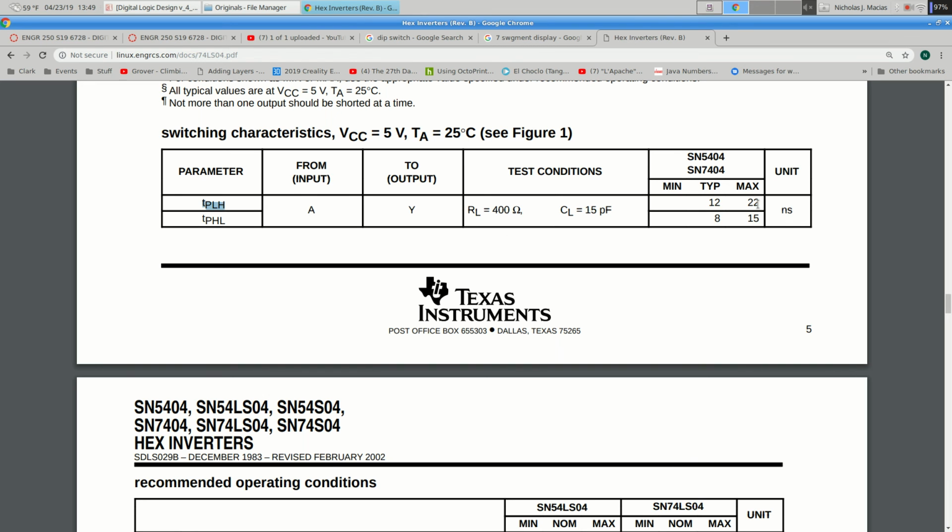And this is always present. There's always a propagation delay, and sometimes we can ignore it. When we're building a 2-bit adder and you're going to flip the switches and see what the output is, we don't care how long it takes. I mean, if it took 5 minutes, that would be a problem, but if it takes nanoseconds, milliseconds, we don't care about that. Sometimes we're actually going to take advantage of this propagation delay. When we start talking about memories, we're going to use this to make some things work. But then sometimes it's really critical, and when we start designing basically computer circuit state machines, we'll have to talk more about propagation delay.